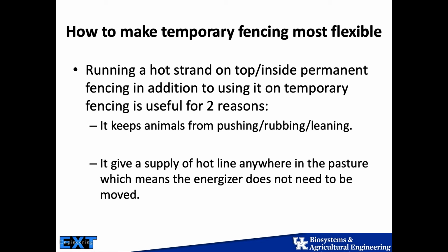I'm glad it's working for you. The spots that I really have issue with it are in spots that I have really rocky soils. Anywhere that's down near a creek, I can usually get away with one ground rod, and it's fine for me to set up a solar box. But in areas where I have really rocky soil, it's really a challenge to get a good ground.